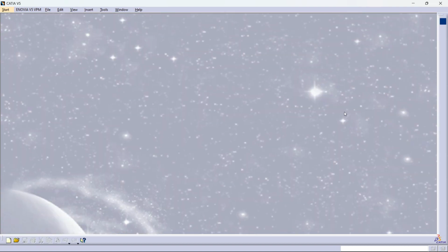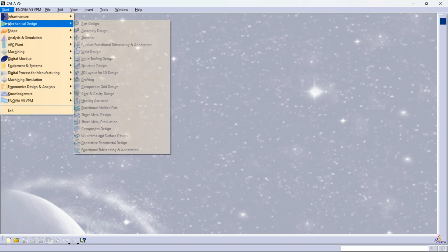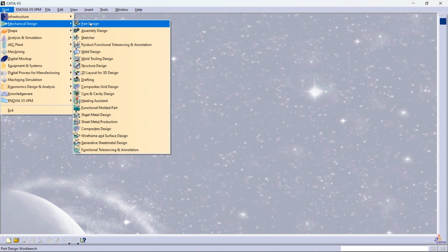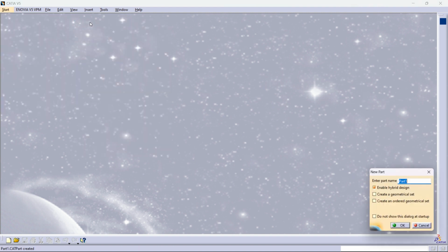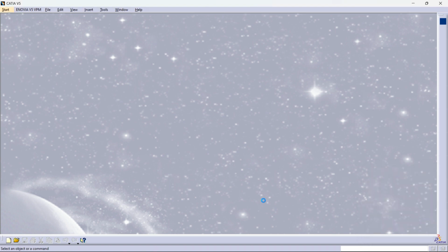To open a new part design, what we have to do is start, mechanical design, go for part design, and it will be asking for a name. We can give a name as per our needs, or use the default name and click OK.